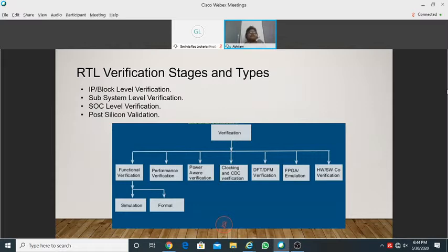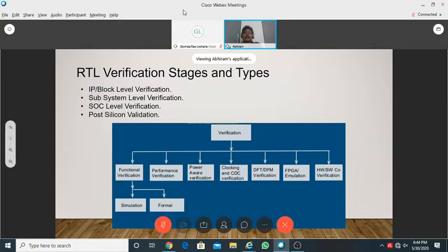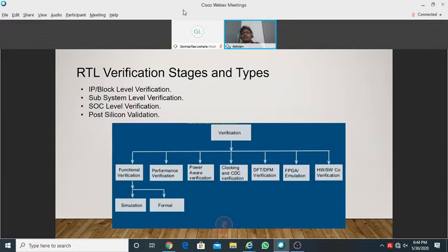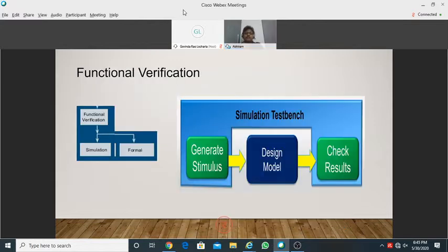They run on machines which have their own limitations, and they have models which have been modeled based on certain assumptions. But now if you want to see how real hardware is working, is it really working as intended? That is where we come into the FPGA prototyping or emulation models.